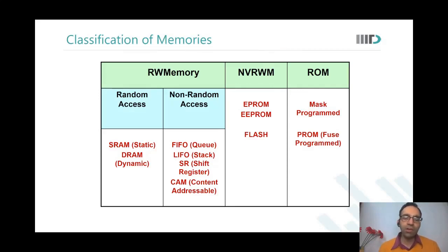We said that depending on the performance requirements from a particular system, I may operate some part of the chip at higher voltage, another part at a lower voltage. You remember this? We discussed all that. So when we operate the system at different operational voltages, naturally the frequency at which those different voltage islands would operate would also be different.